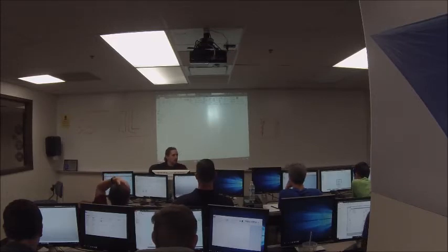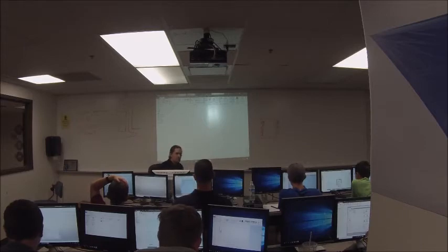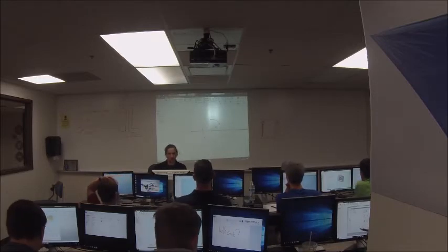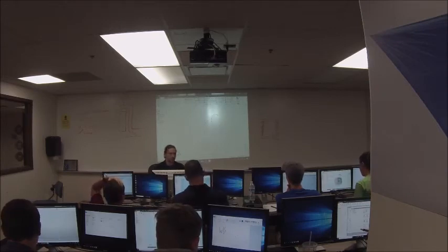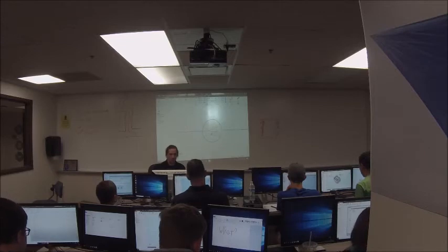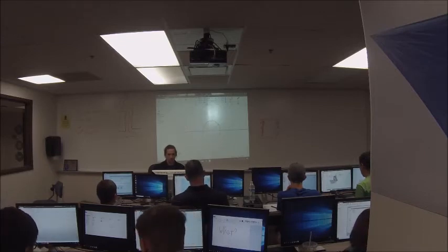And when you need to change something, you can go over and find that sketch that you needed to change or that extrusion that you needed to change, and you can double click on it and edit that part. So I want to change the diameter to 1 3/4. Actually, let me back out of this and do this again so you can see. So I'm going to the sketch, double click on the sketch, that edits the sketch again. I can double click on my dimensions, change dimensions, click OK, finish the sketch. You can see my part got smaller.